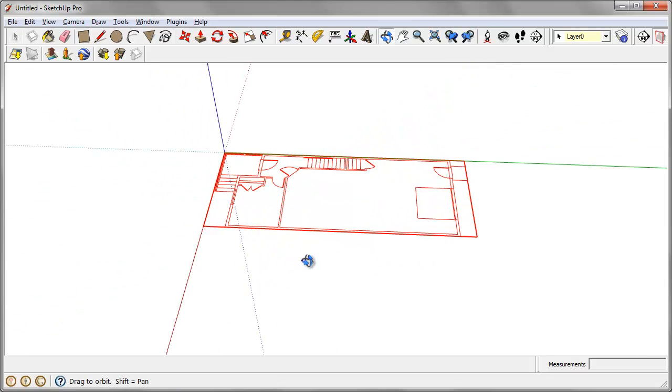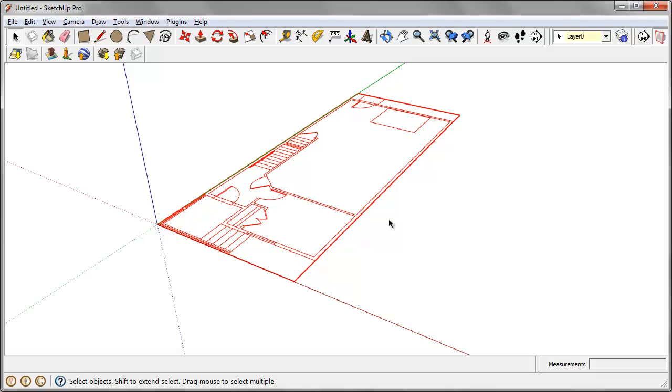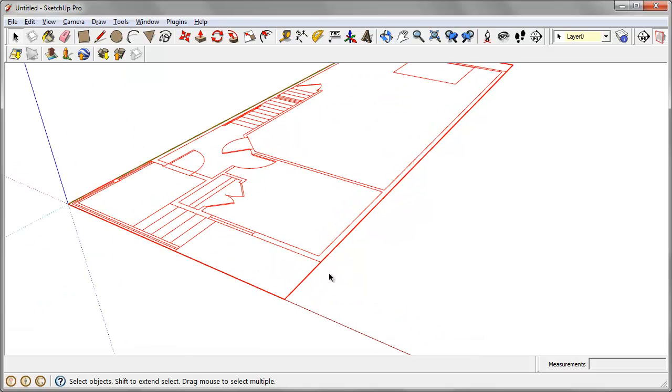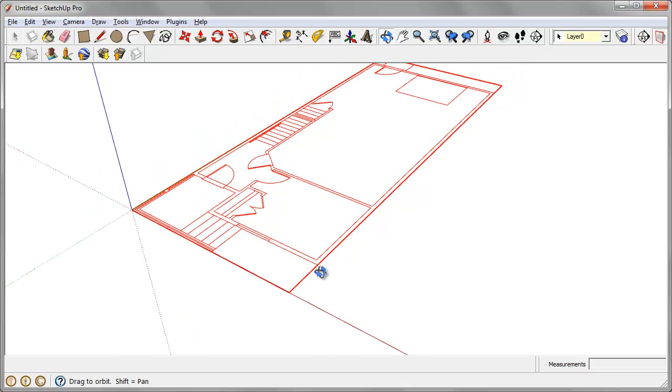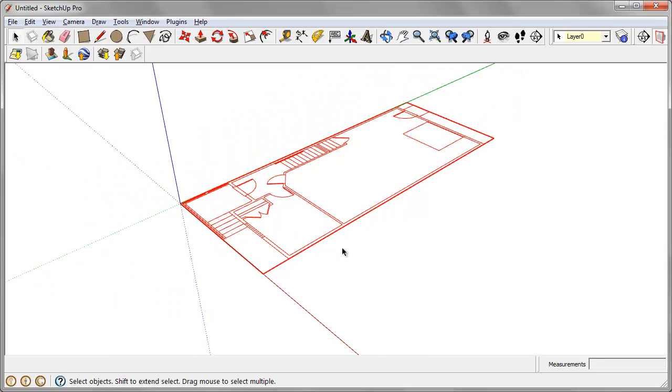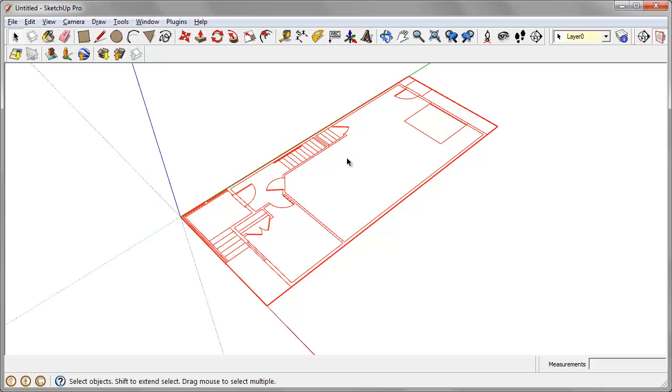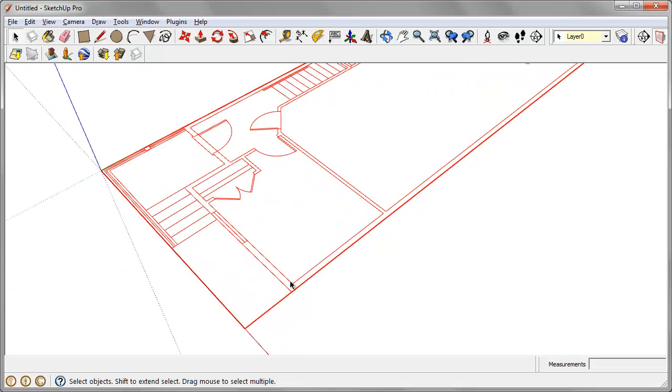Okay, so modeling from this CAD plan, the common tendency would be to want to fill in these surfaces and create surfaces in SketchUp and then extrude it vertically. And there's one big problem with this, and that is that most CAD plans are not perfectly drawn. A lot of people don't adhere to the standards, and they'll just have things kind of off axis and not drawn correctly. Maybe edges don't meet. So typically it's best to just lock that CAD drawing as a background and then basically recreate it. It's okay though, it's really easy to recreate.